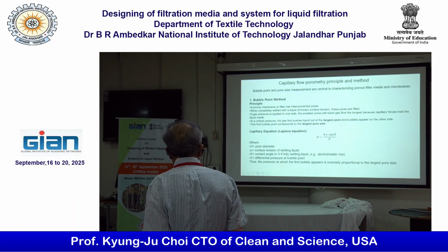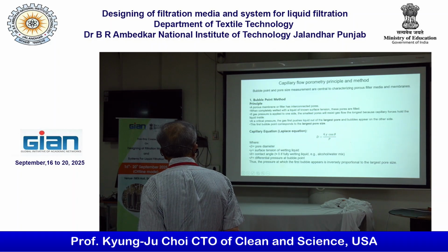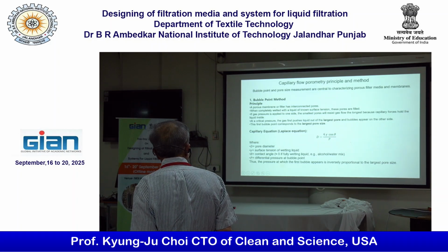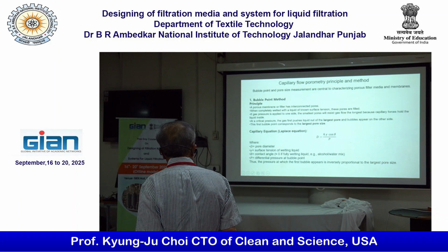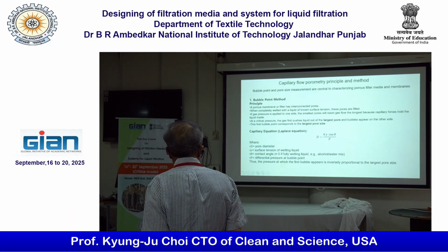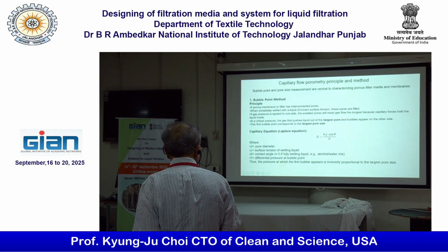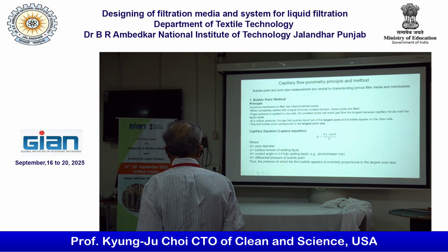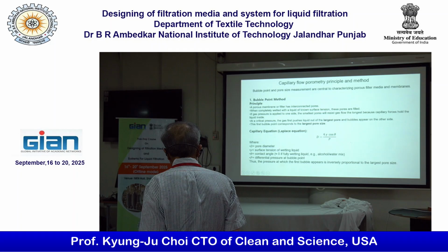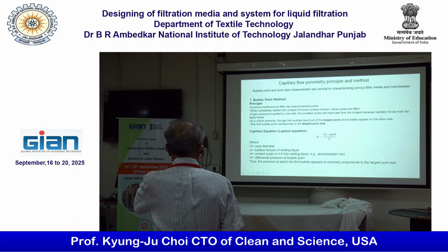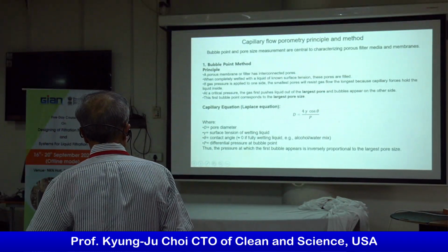The gas pressure is applied on one side, and the smallest pore resists transfer. This one we call the bubble point. The bubble point is where the largest pore bubbles up. When you look at the Laplace equation, actually we got the Washburn equation. The Laplace equation comes before the Washburn equation.